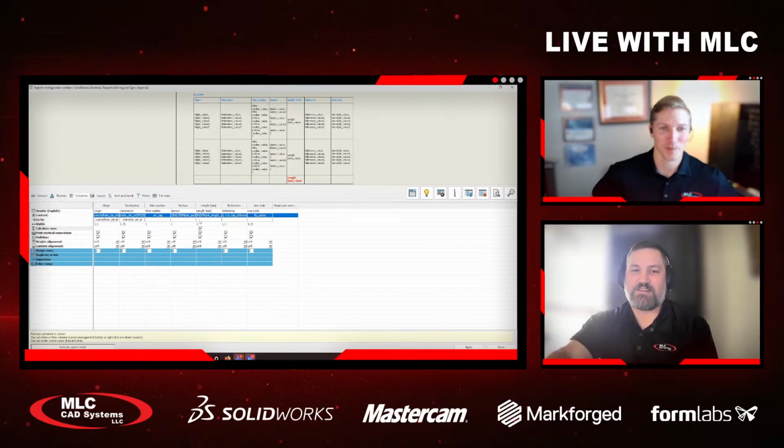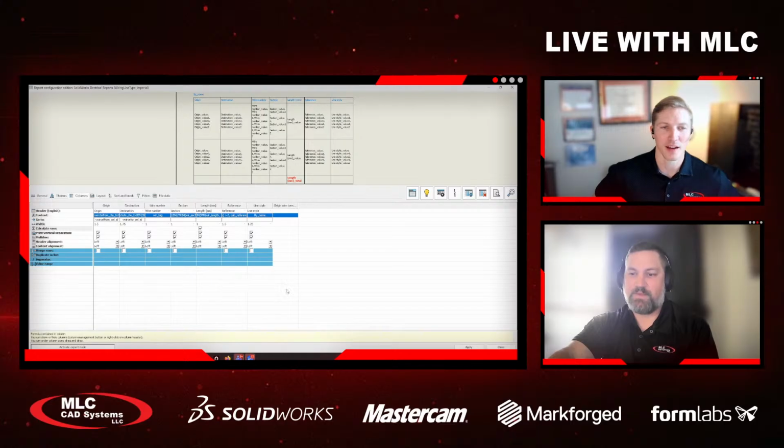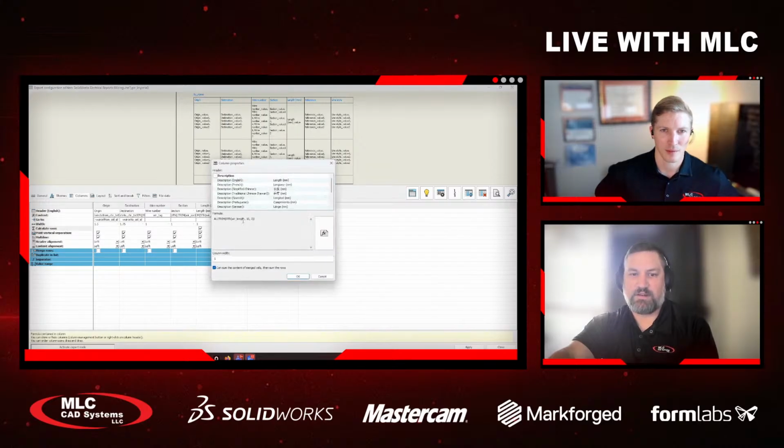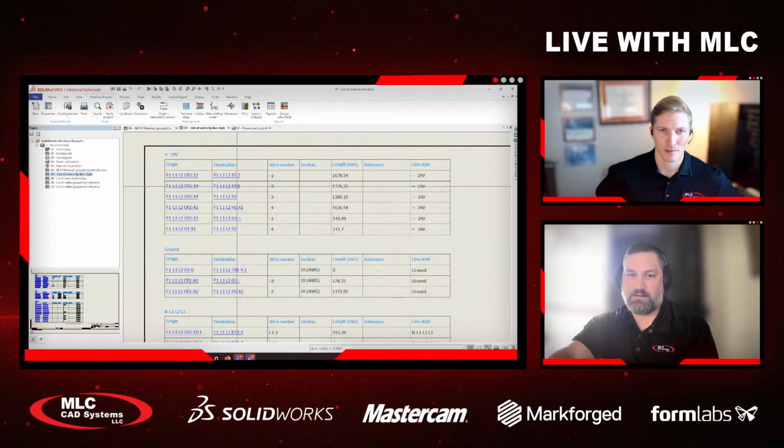I will say that that's a number one thing that I see on reports. People want the total length, but that has not been checked. So make sure that that is checked. Okay. So now we're going to calculate the sum. You can see this row has that checked. And this wire length by default, you'll see it's going to trim this wire length, and then we're going to sum it up. I'm going to hit apply here, and then I'm going to hit close. Now, again, we made a change, so we've got to update our report configuration or update our drawing.